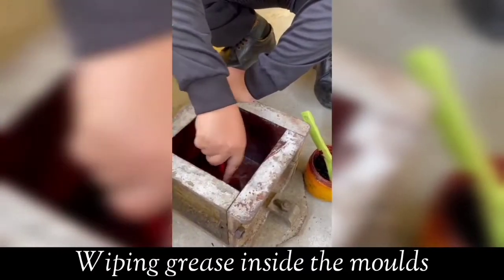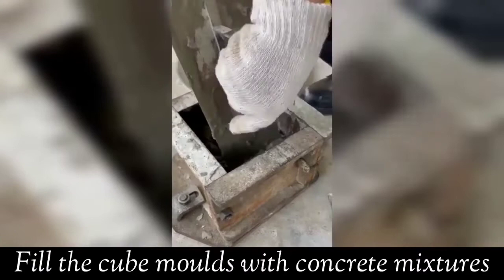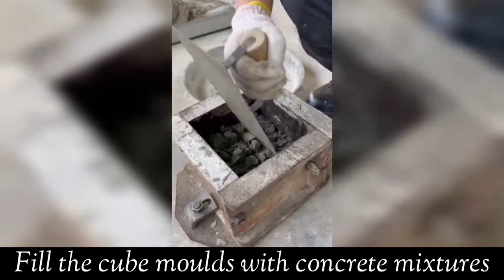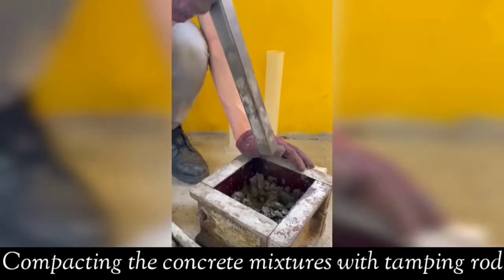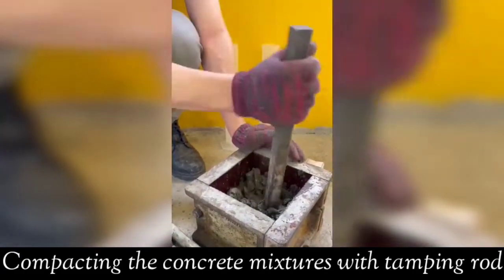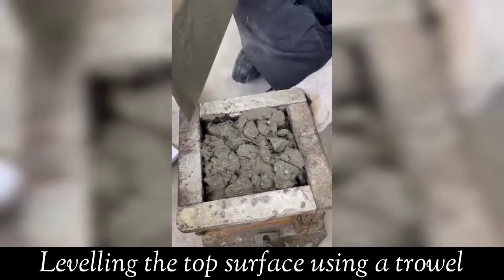The cube mold is cleaned, then grease is applied inside the concrete cube mold. Fill the concrete mixture in the molds in layers approximately 5 cm thick. Each layer of concrete mixture is compacted with not less than 35 strokes per layer using a tamping rod. Then, level the top surface and smoothen it with a trowel.